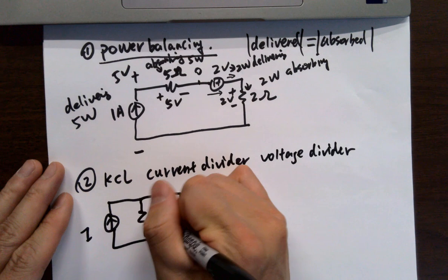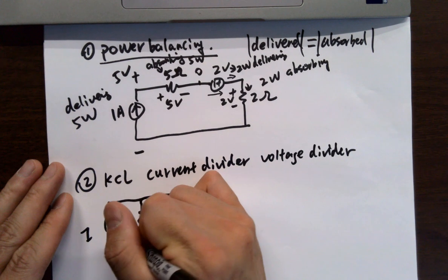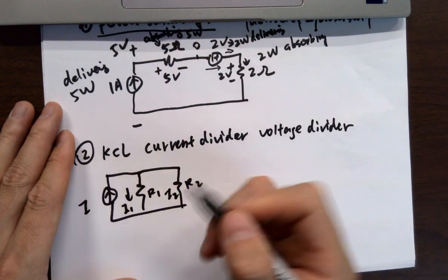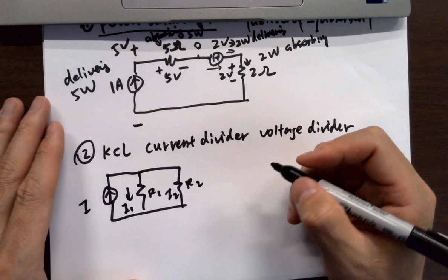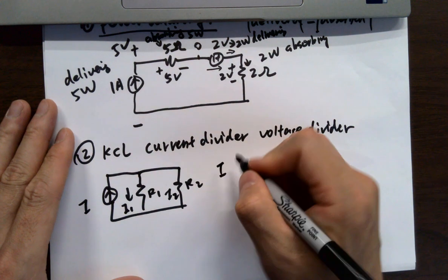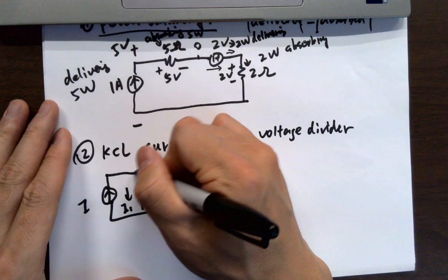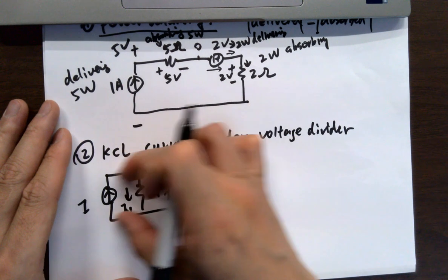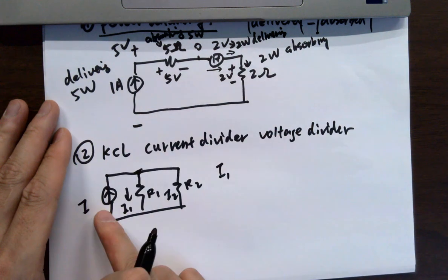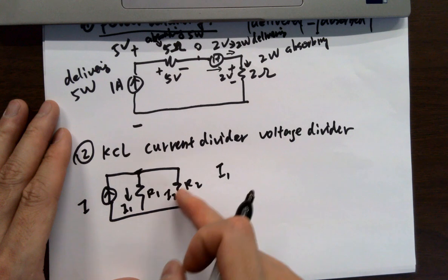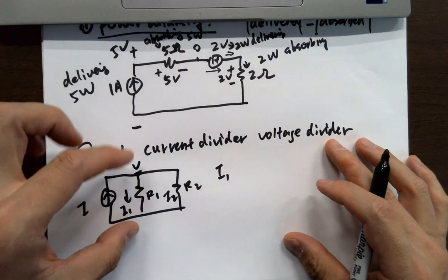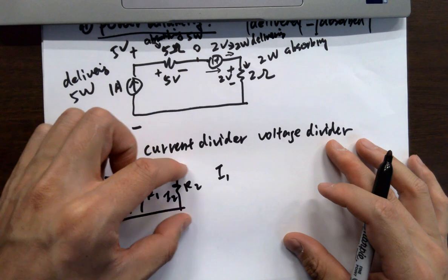I, R1, R2, I1, I2. I started using the conclusion for the rest of the semester, but when we try to derive I1 and I2, it's basically using the common voltage for all these shared nodes. Remember? The reason we can apply current divider theory for this kind of circuit is because they have the shared common voltage on the top, or the voltage drop across the two terminals.